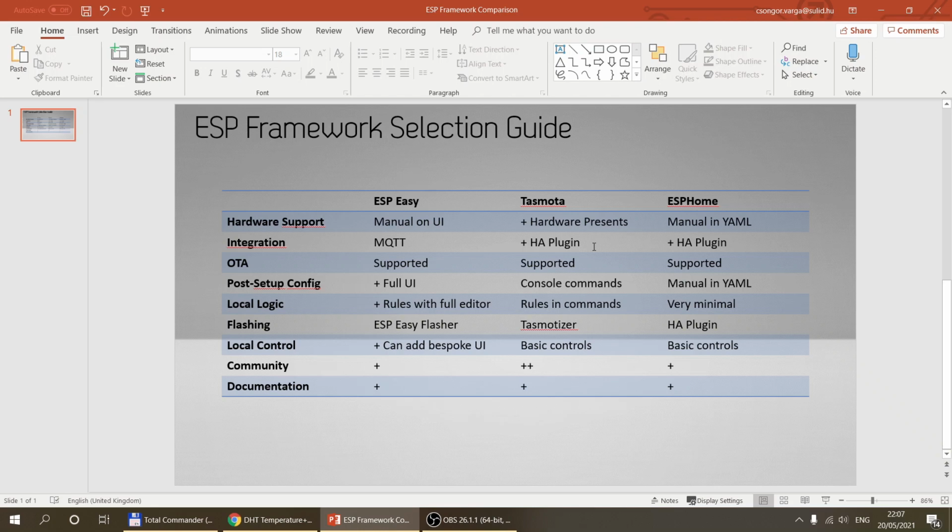But I think there are specific cases where the hardware actually has a limitation with ESPHome or Tasmota. So, for example, if you are using a Sonoff Basic or any of the ESP based commercially available hardware, so Sonoff or Blitzwolf, they have an ESP which comes with a 1 megabyte flash chip. So the memory inside is very limited. So again, what can be included in the code is also very limited.